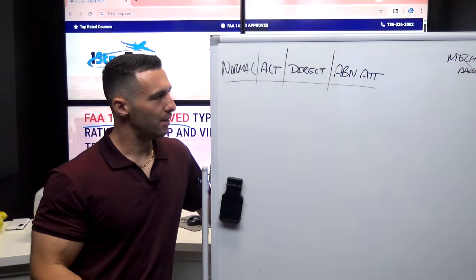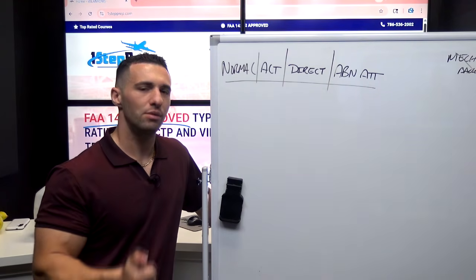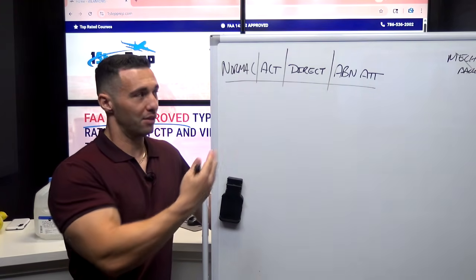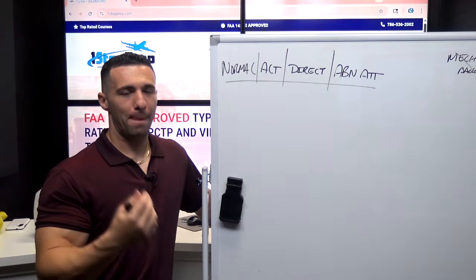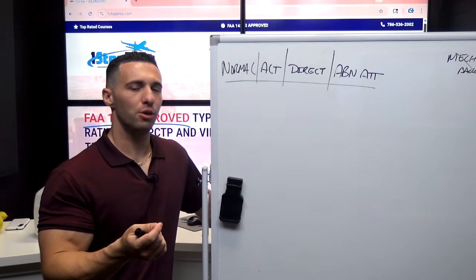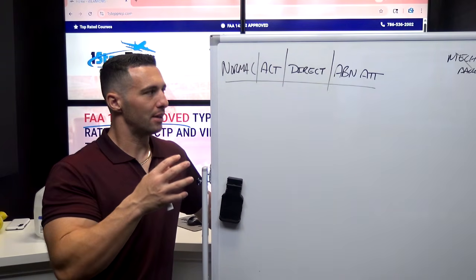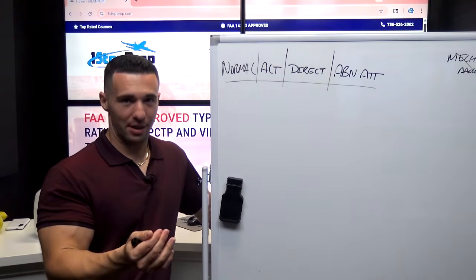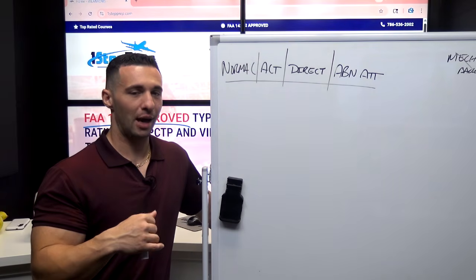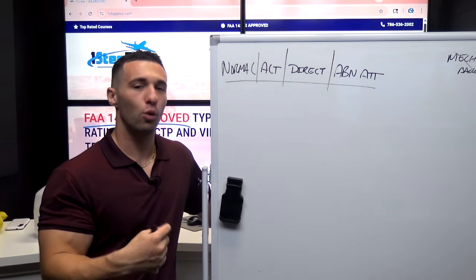I will say, if you find yourself in an abnormal attitude and you have this law active, for the moment that you don't have that G-load protection, it's imperative that you prioritize airspeed and not necessarily over G'ing. I would rather over speed than over G.